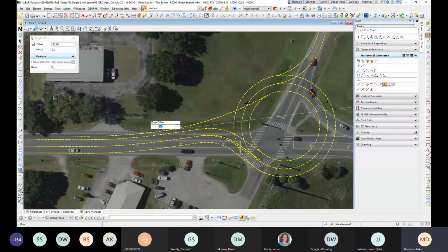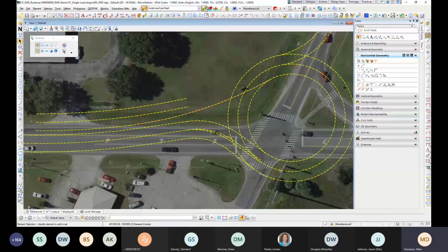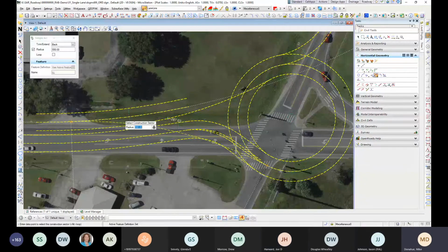Offset that 12 feet again. 2 lanes. So I know at this point here, I want to be 12 feet across for each lane. So this is where I want to be. And I'll allow my transition to the 14-foot width to occur from this point tangential to the lane lines within my roundabout. And again, I like to use guides to let me know where I'm at. So I'll draw from this point over 24 feet to the center of that arc. And then as I place these radii, getting a lot of feedback. You can see I can shorten this up a little bit and still be 24 feet across at that location.